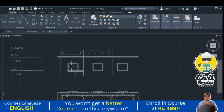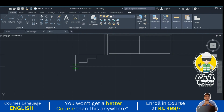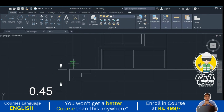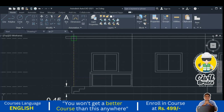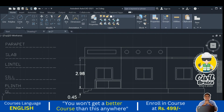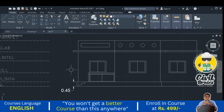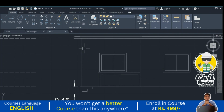Okay, so next we need to show the dimensions. Height of the plinth. Next, sill height we don't need to show, just show the lintel bottom, 2 point, okay sorry, it is slab bottom, it is coming 2.98. Our slab bottom is 3 meter, right?